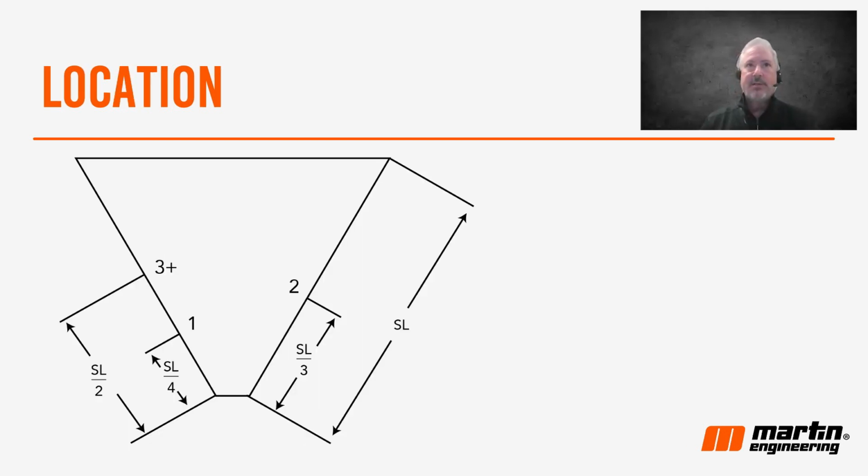One of the considerations is the location. Location matters on where we're going to put these devices. The standard rule of thumb, and again, rules of thumb, there's deviations from it. Sometimes it's based on available area to mount. There could be barriers or restrictions or stiffeners or other things in place. Ideally, if you look at the lower left where the number 1 is shown, that is 1/4 of the slope length up from the discharge. The vast majority of applications we work with, we apply one vibrator, properly sized and applied to move material. That's typically where we want to have that vibrator installed.